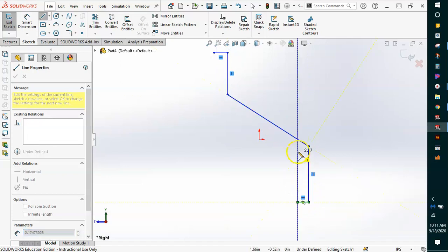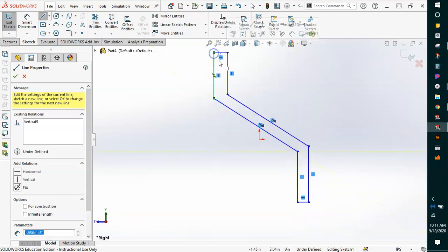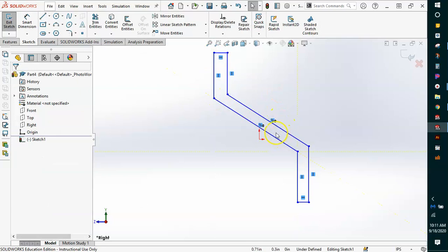So it just wiggles down like that and back up. Now, if you haven't done so already, like my computer did, I tried to make sure I drew on horizontal and vertical lines for these three. Same thing with these three. And mine defaulted to making these parallel. So I made sure when I drew this line up, it was parallel. If yours are not parallel, select both of them holding Shift and set them to parallel.